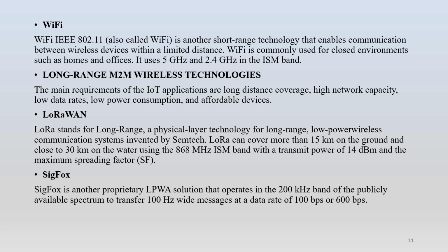Coming to LoRaWAN, LoRa stands for Long Range, a physical layer technology for long range, low power wireless communication system invented by Semtech. LoRa can cover more than 15 km on the ground and close to 30 km on the water using the 868 MHz ISM band with a transmit power of 14 dBm and the maximum spreading factor.